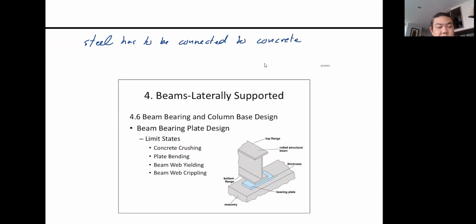Most of the time, when you have a steel building, you cannot have a steel foundation, right? Because of the exposure to the soil conditions and so on. So even if you have steel columns coming down, when you want to connect your steel column to the foundation, the footing of the foundation has to be concrete. And part of the footing, you have the abutment, correct?